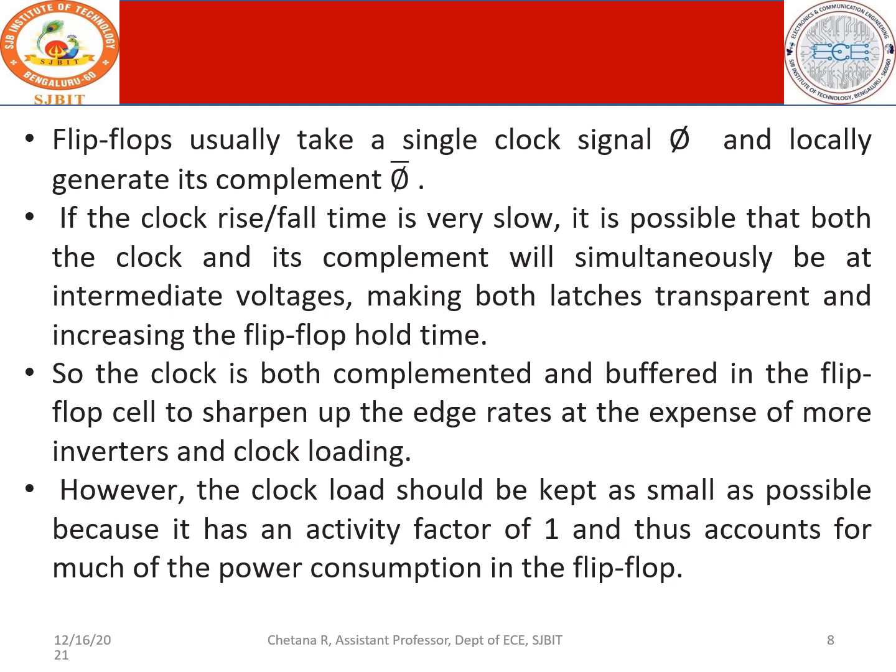If the clock rise or fall time is very slow, it is possible that both the clock and its complement will simultaneously be at intermediate voltages, making both latches transparent and increasing the flip-flop hold time. Therefore, the latches are transparent and the hold time is increased.